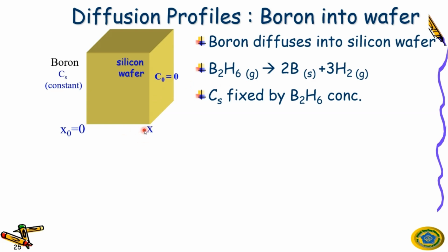So we start to do a diffusion. We start, and then you can see the concentration on the surface. The boron concentration on the surface is the highest. Of course, this is CS, and it gradually decreases, right? Because boron starts to run from the surface to the end here. So this is flux from the left to the right, and you know that the concentration here will be smaller than this one, because this holds as a constant always.